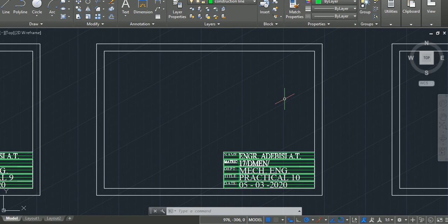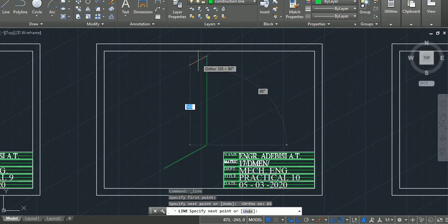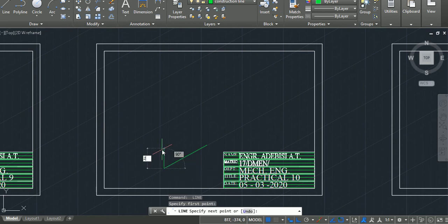So let's begin. First, I'm making sure my drawing is in isometric mode. All I need to do is start with the line tool. I'm intentionally using the line tool because I may need to erase some. Then I'll also put my drawing on auto mode since most of what I will be drawing follows the axis. Now my drawing is a little bigger than what it should be, but I do not mind because after drawing I can always scale it up or scale it down.